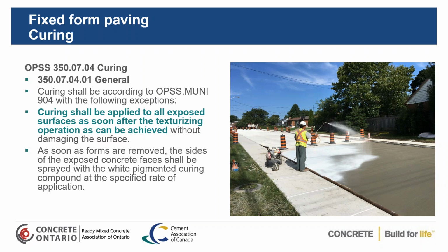Now, one thing you have to make sure of is that when the forms are taken off, you're going to go through and put curing compound on the sides. Here, you don't have to because you've got sidewalks as part of it, but if this was an exposed area, you'd have to put curing compound on the side to keep that moisture in the concrete.